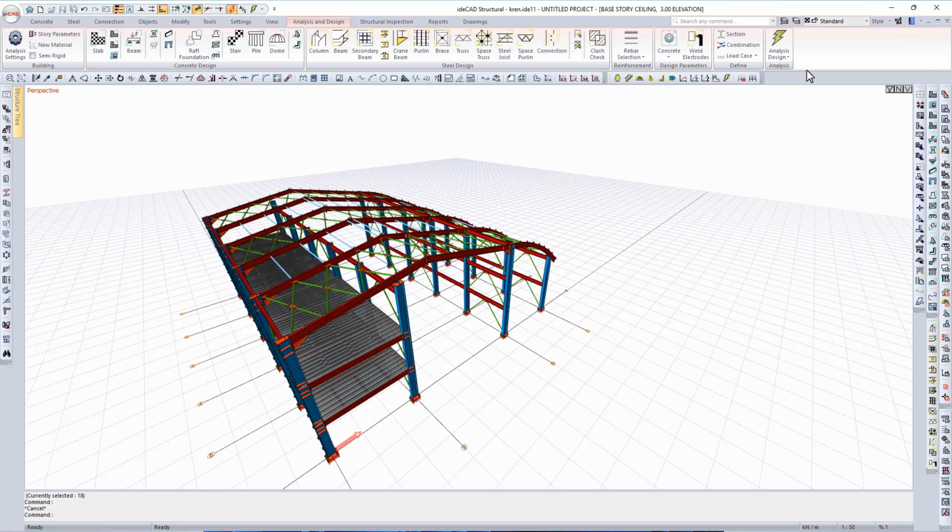And that's it. By properly identifying your seismic frame types, you enable all the special seismic checks required by code. The design reports will reflect all applicable provisions, ensuring full compliance with AISC 341-16.